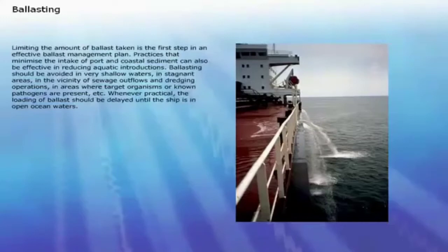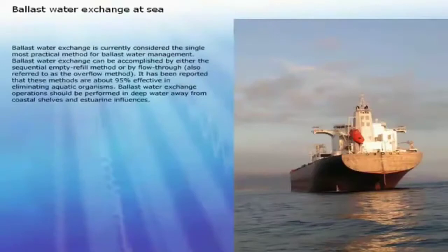In stagnant areas, in the vicinity of sewage outflows and dredging operations, in areas where target organisms or known pathogens are present, etc. Whenever practical, the loading of ballast should be delayed until the ship is in open ocean waters. Ballast water exchange is currently considered the single most practical method for ballast water management.